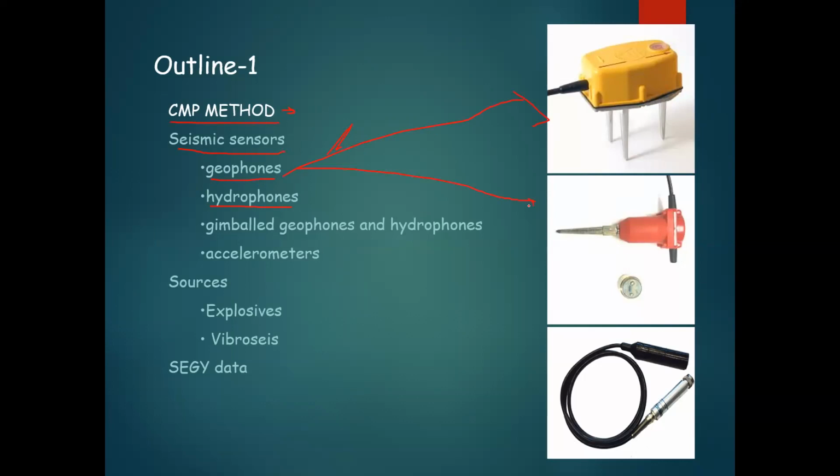I have already discussed that this is a 3-component geophone, a 3C geophone. It records seismic data in vertical and horizontal fashion. There is one vertical component and two horizontal components. The horizontal components are easting and northing, E for easting and N for northing, and this is Z, that is depth, vertical. And this is a single component geophone, which records only the vertical component.